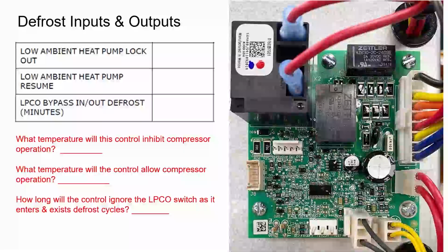And in the Pacific Northwest, specifically central Washington, southeastern Washington, western Idaho, and a little bit of western Montana and northern Idaho, we can see some issues where that low pressure switch was actually tripping at about the minute to minute 30 mark. And so we had to extend out that low pressure bypass to 3 minutes. So all of the new boards are 3 minutes.